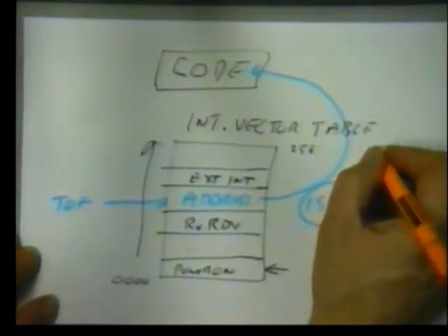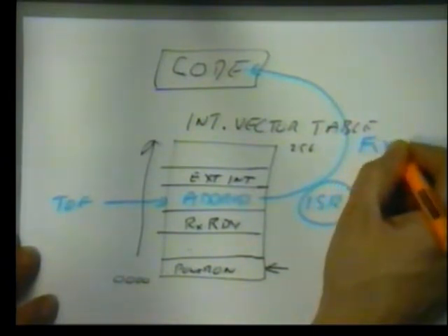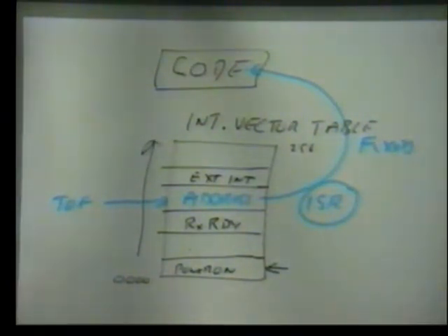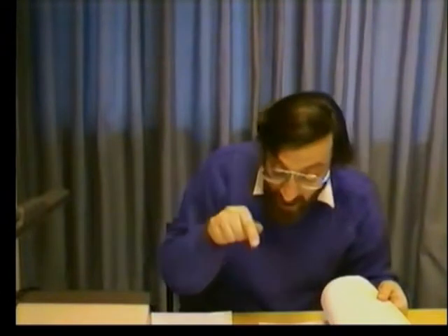So the interrupt vector table, that is fixed in memory. It's an absolute memory location. You can go to the manual of the processor, you can look it up. It says, right, serial interrupt vector will always be at memory location such and such. It's a universal constant. It's in the data book. But you write into that memory location the actual position of where the interrupt service routine is. It's a redirection table, really. That's why it's called a vector, because it points us to where we have to go.